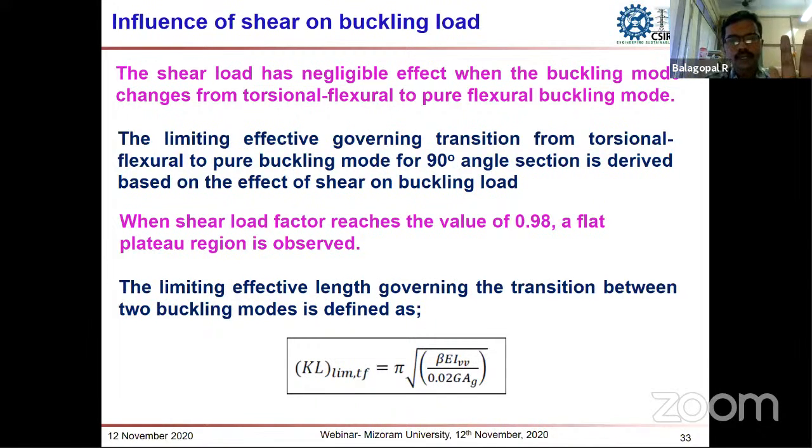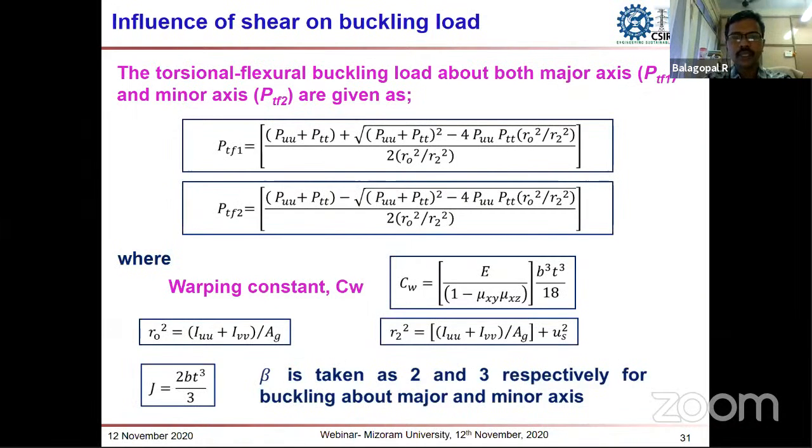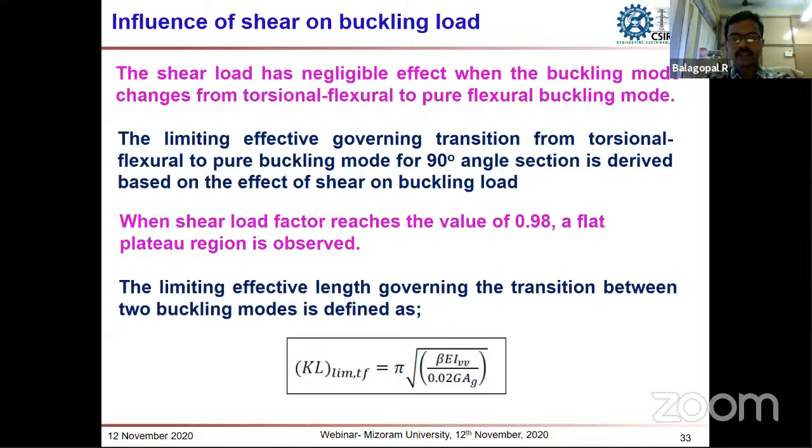We have proposed considering that once the shear load factor reaches the value of 0.8, the flat plateau is observed. By substituting these values in the above equations, we have arrived at this limiting value for the slenderness ratio.